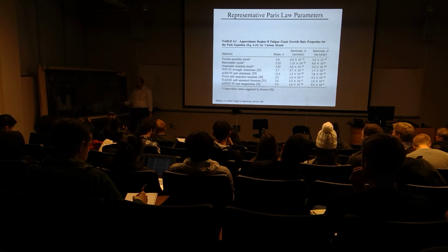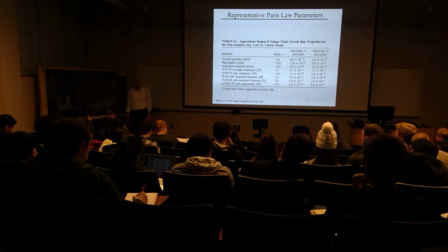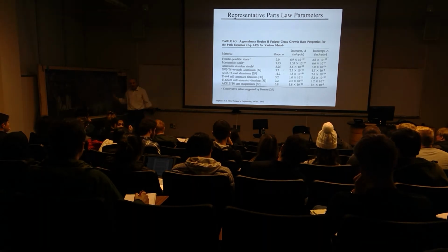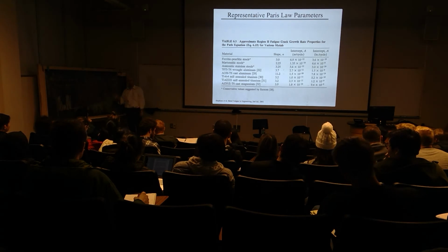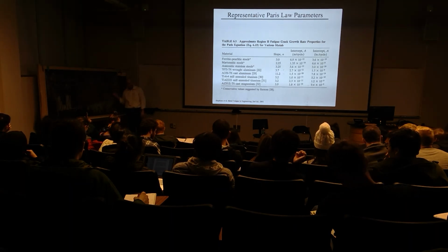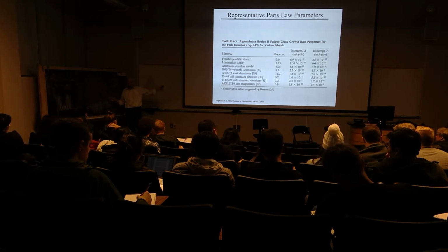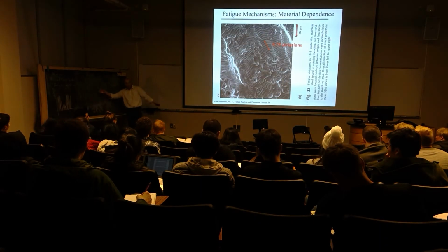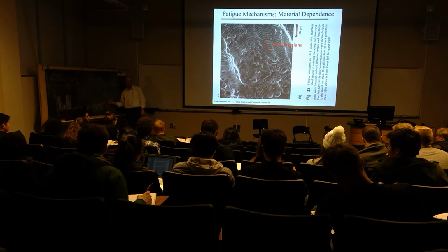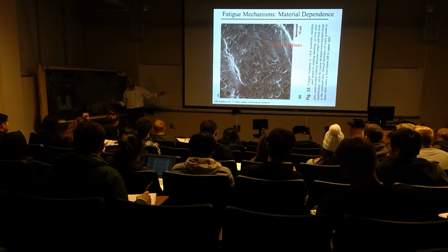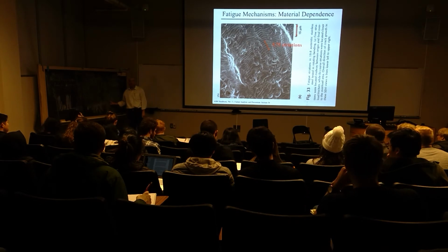So I don't have enough time to go through this here because I want to move on. But I'm going to send you an example of using exactly that for this problem and go through the rest of it, and give you the information about calculating and estimating the maximum cyclic stress in this particular material from this data that we just developed, the dA/dN. But the most important part is using the striations for something that's valuable, okay? And that's getting an estimate of how fast that crack is going every cycle.